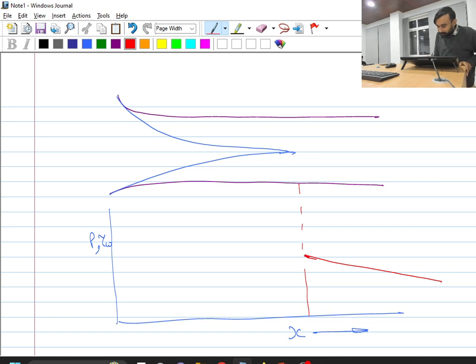But before this, because you have more viscous effect, why after this will it be a straight line? Because after this point your velocity profile has become constant. Okay, so let me put only pressure over here. Okay, so after this point your velocity profile has become constant, so because of this your wall shear stress will be constant.